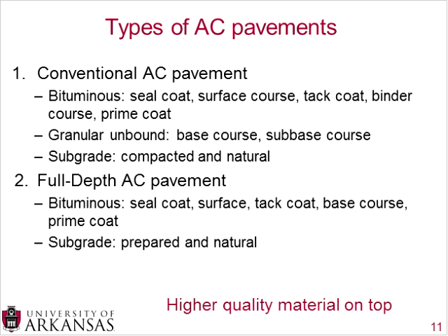One thing to remember also about AC pavements is because you have all of these layers, you generally have higher quality material along the top on those surface layers, and then as you go down, the material quality goes down a little bit. Now that's not to say that what's underneath is not adequate for its needs, but you don't need that smooth riding surface on the top, which generally has a little bit more asphalt cement in it. So you can have slightly larger rocks, slightly less asphalt cement in those lower materials, so it may not be as strong, but it does provide the structure that's necessary for the pavement.